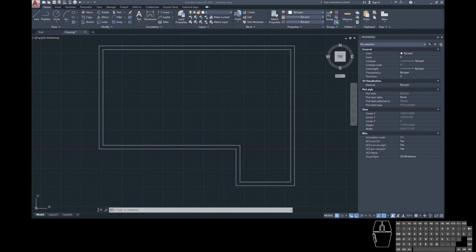In preparation for workshop number 2, we're going to finish up the line work for both the plan and the section drawing. We're going to use the offset tool a lot, we're going to use trim a lot. All of the tools that we've gone through today are going to enable us to finish up the line work for both of these drawings. The remainder of this recording is just going to be me doing a quick speed run through. I'm not going to narrate it, but it's going to be an example for you as to one way to go about drawing the rest of this line work.